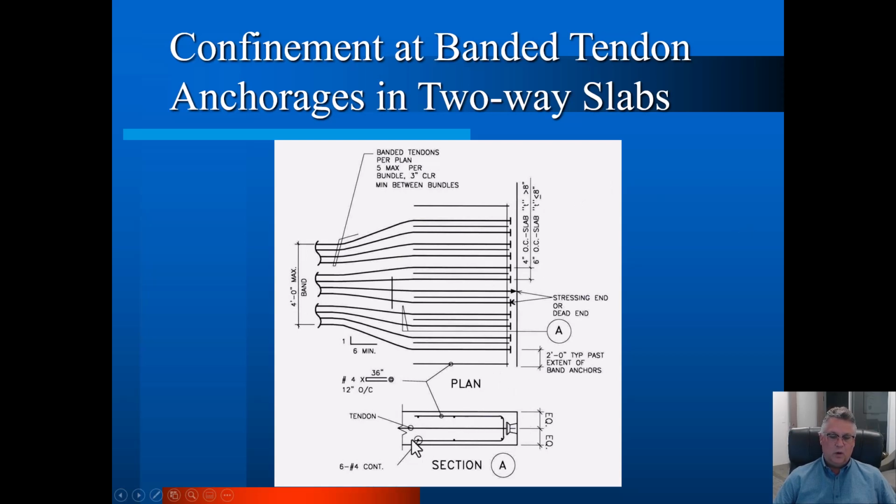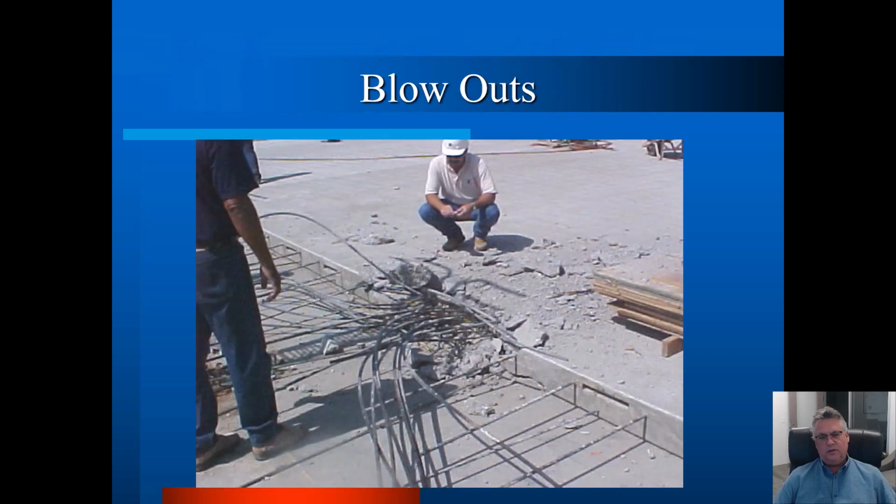So we, one way or the other, need to reinforce that location and confine it. This is a detail that we use for some thicker podium type slabs. In our thinner slabs, we actually use stud rails themselves now to confine that concrete. But this was a condition on one of our jobs in Fullerton where there was a little misunderstanding between us and the contractor. We had all of our confinement details on the job.